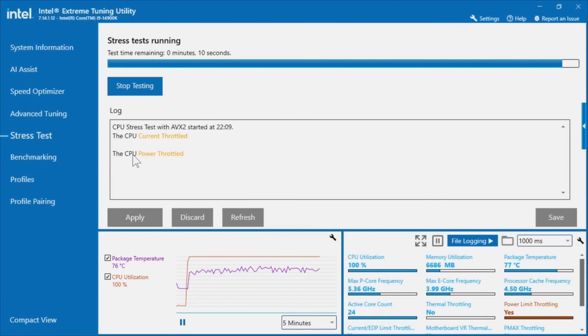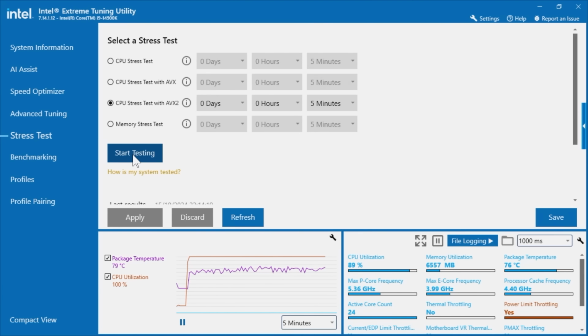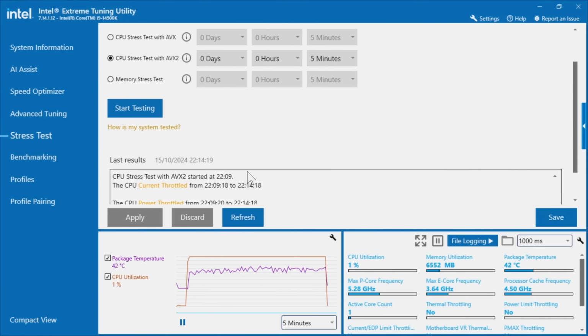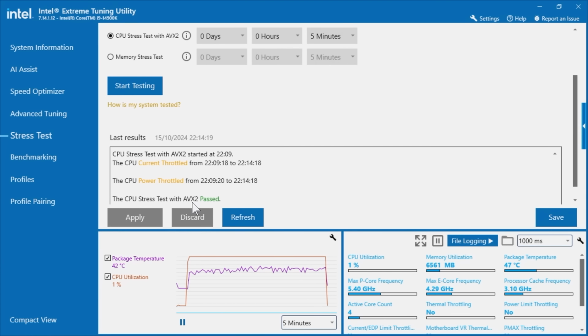And remember, before the BIOS updates and before the undervolting, some of these processors were hitting firmware throttle during the course of this test, and actually failing even with no undervolt applied, with a standard Asus BIOS, and even with the Intel default settings. I've actually run this with the Intel default settings, and the test has failed on numerous occasions, which is quite worrying. So undervolting and syncing all cores certainly is a way forward.